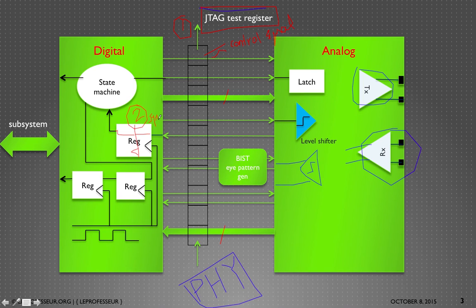Different technologies have different sync requirements, so check with your company's technology team how many registers or flip-flops you would need to synchronize the signal. So that's the important takeaway: the signal which is coming from the analog part and going to the digital part, you're going to use it after synchronization. Remember, that is very important. Otherwise your chip or your IP is not going to work well.